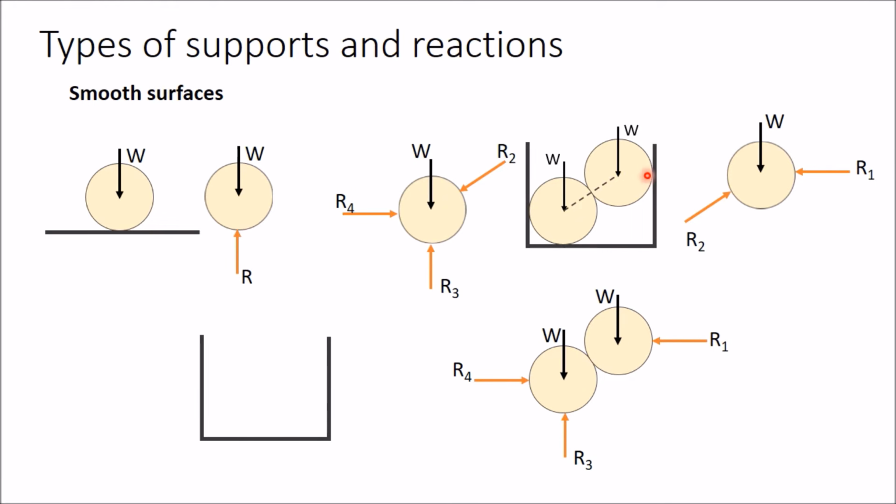Now if you want to draw the free body diagram of this drum, you can draw this drum first. Now one contact point is here, so here you should show one reaction. This reaction is R1. So whatever direction you have taken here, you have to take the opposite direction here. So the name is the same, R1, but the direction is opposite: there you took the left side, so here you have to take the right side.